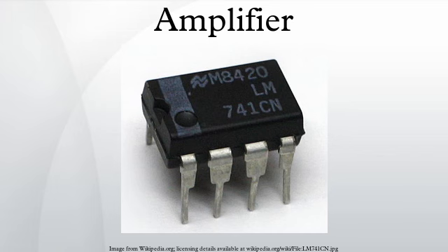The main advantage of a Class D amplifier is power efficiency. Because the output pulses have a fixed amplitude, the switching elements, in which bipolar transistors were once used, are switched either completely on or completely off, rather than operated in linear mode. A MOSFET operates with the lowest resistance when fully on and thus has the lowest power dissipation when in that condition.